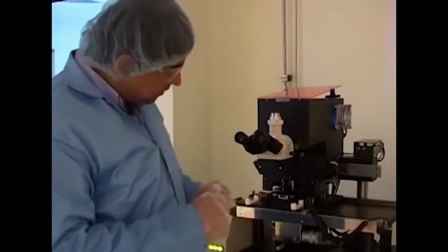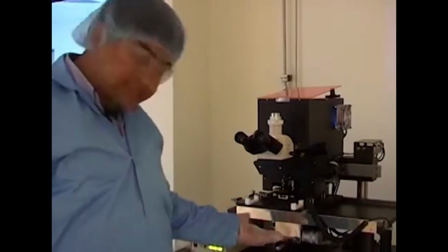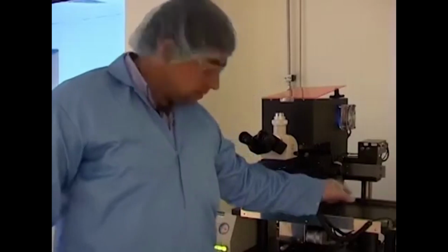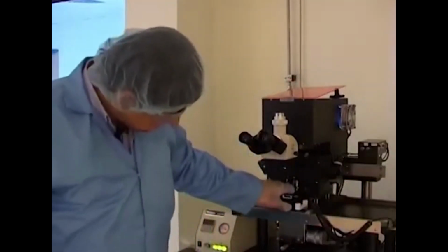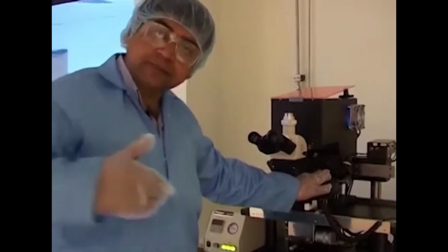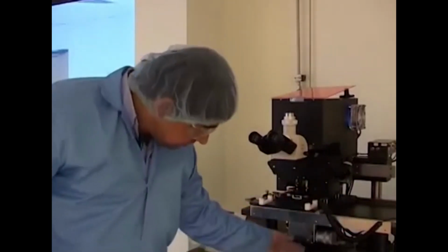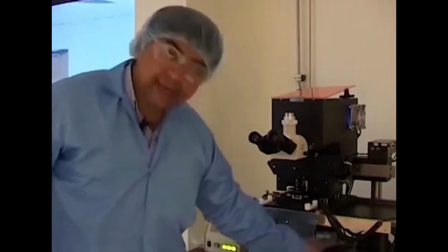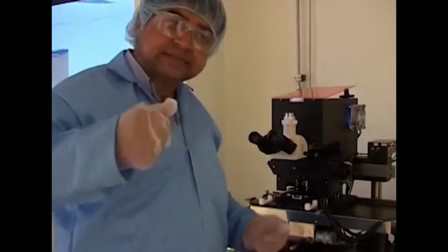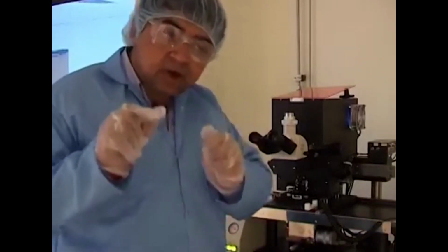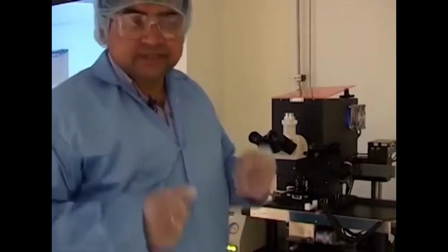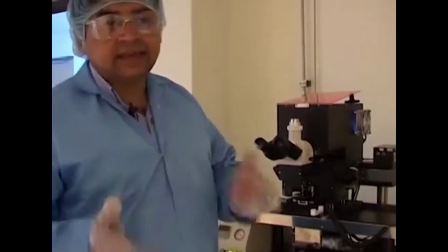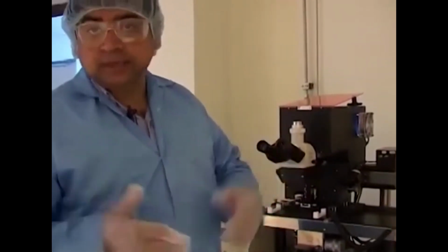And the idea is we should be able to move the wafer stage. Okay, and we do it by moving this, which is the X displacement, and this is the Y displacement for the scope. So the scope can position on a particular area, and the wafer stage can be moved by the controls at the bottom here in this particular zone, and we can move the Z displacement and see whether the feature on the mask is really in focus. If it is in focus, that's an indication that the wafer has touched the mask surface, and that is the spot at which we should do the exposure.